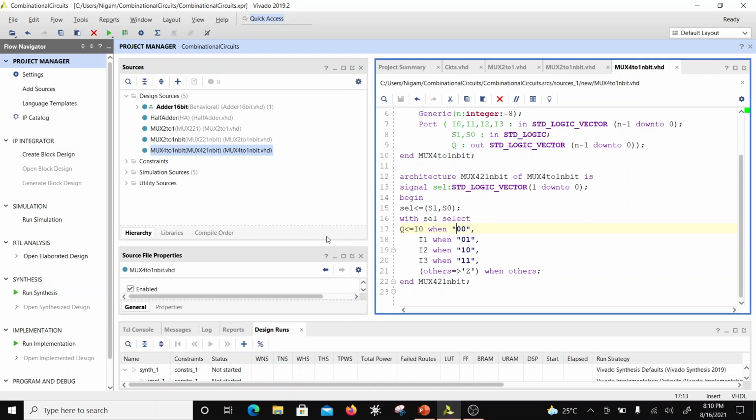Let's assume that each one of the inputs is going to drive a bus, and that bus is nothing but a std_logic_vector. Which one it is going to put onto that bus will be decided by a decoder and an output buffer, right? So we need to create a circuit which is called a buffer.